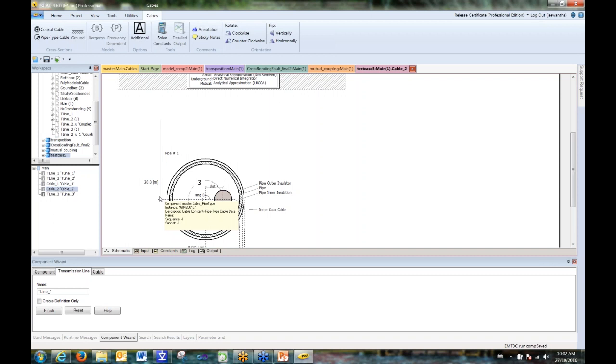The other question is, in the GPR calculation, ground potential rise in stations, how we should connect the sheath. You can go either way. You can ground them individually, or you can ground them with the substation system. The whole point is you have to maintain the correct grounding resistance. As long as you put the correct grounding resistance, it doesn't matter whether you have individually grounded those cables or you just connected them with the substation earthing system. So the importance is the correct grounding resistance representation.